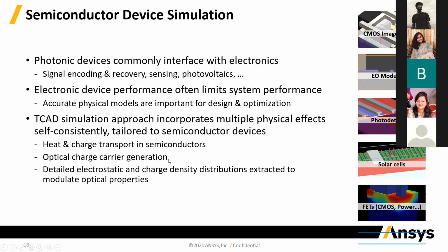This is relevant for solar cells. And in your electrical simulations, you can also get more insight into the electrical transport. You can get the electrostatic profile for your device, the carrier density concentration in your solar cell or your photodetector or modulators. All of this information can come out from the charge simulation.